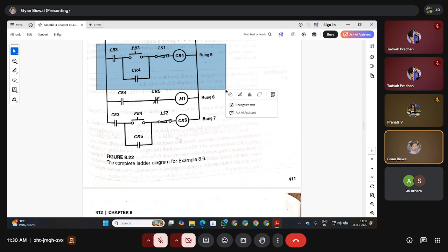That's all. Okay. So what will it do? CR3, right? Why am I bringing CR3 here? Because CR3 is a master control relay. So it will operate both the upward direction and the downward direction, and it will also avoid any conflict of interest between the upward direction and the downward direction whenever the elevator is moving. How will it execute? That's the reason we are keeping CR3 at the very beginning, to take care of everything. Okay? It's like an entry gate.